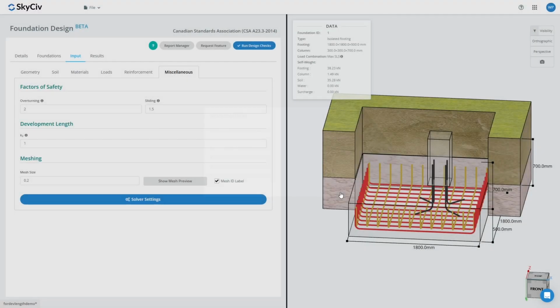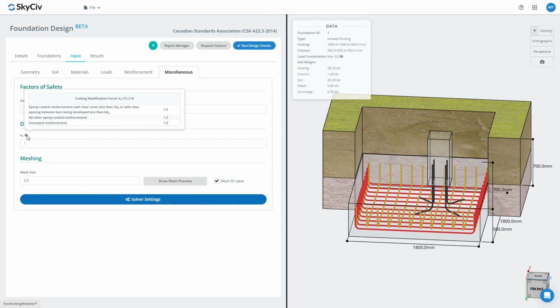You might also wonder why some K factors or the development length factors have disappeared on this update. Well, this is because the module now auto-calculates them. This includes the bar location factor, concrete density factor, and bar size factor. So one might ask if this is true with other design codes. The answer is yes.